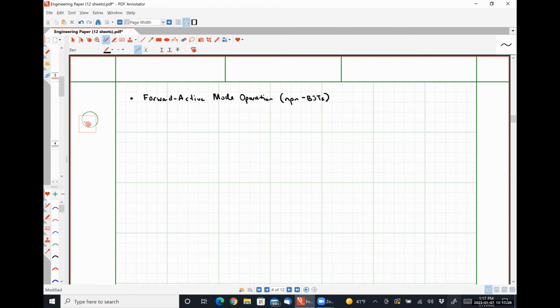So let's start by drawing a rather large sandwich structure. Okay. So I'm going to call this terminal up here my collector. And then I'm going to have a large collector region, which is doped N-type. Here in the middle of my sandwich is my base region, which is heavily P-doped.